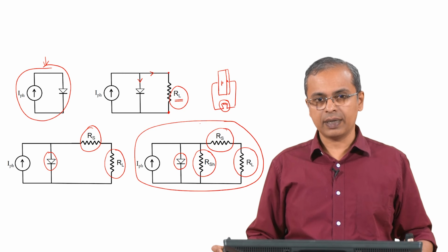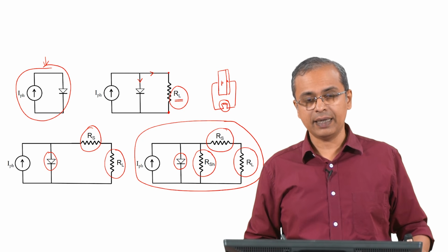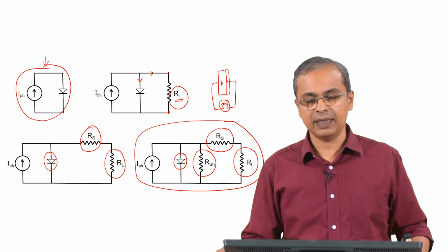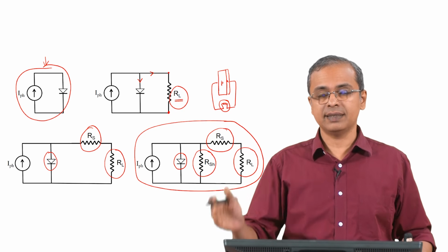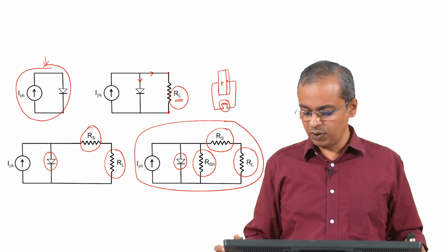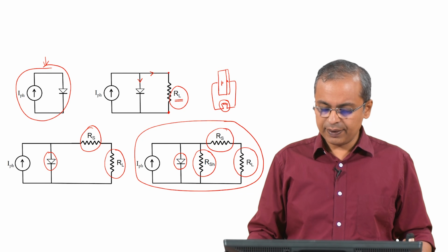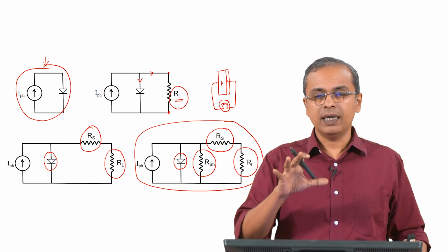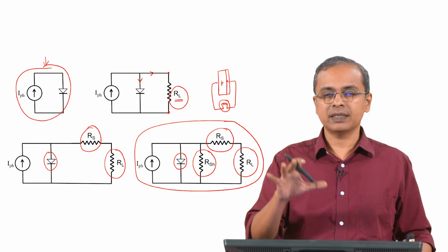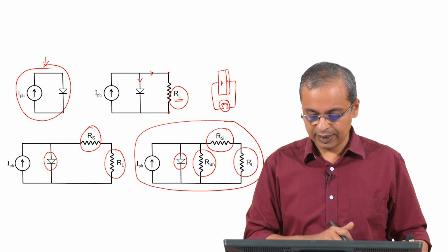Okay. So, you have lot of processes going on, you have the photocurrent that is generated, you have the diode operating internally itself, the diode is there, it is operating in forward bias, you have a shunt resistor which is representing the recombination events that are happening, you have a resistor in series which represents the idea that there is current going through that solar cell before it even comes out of the circuit, and then finally you have your load resistance. So, this is your overall circuit. Okay. So, these are all the various parameters of how the solar cell behaves when you have incoming radiation. So, the purpose of this class was to look at how the PN junction and therefore the solar cell based on the PN junction, how does it behave with respect to the incoming solar radiation.